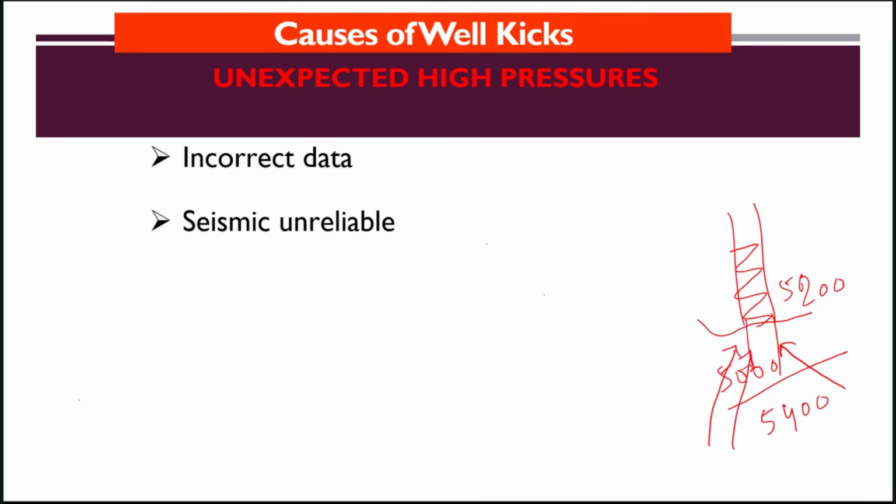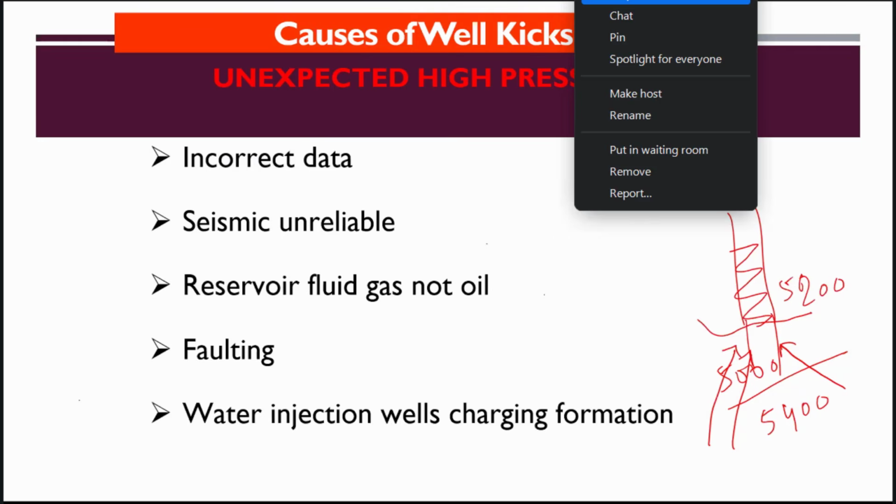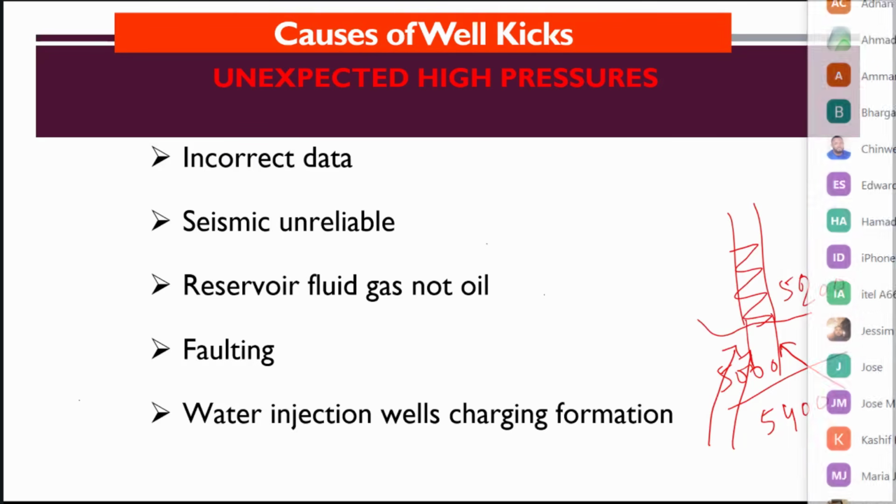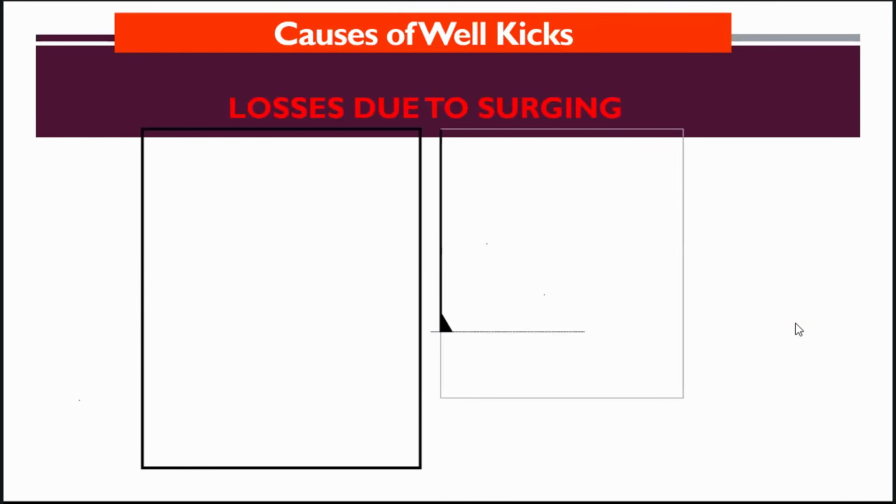So either your mud weight will be low or your formation pressure will be higher than expected to get a kick. Kicks can also be due to faulting, water injection, charging of sand, or artesian effect. All those factors we have seen already.